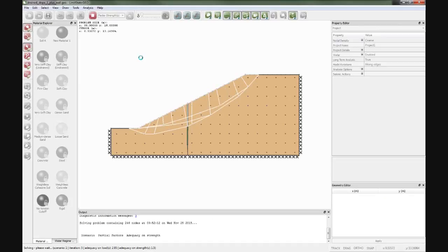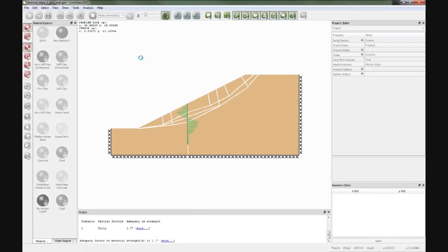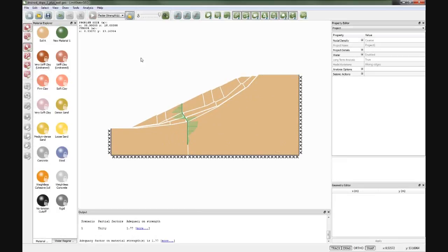The software will simply cause a failure mechanism where that sheet pile wall bends. So you can determine what sort of bending strength is required to avoid a ULS. And do remember this is ULS software, so that's required for ULS. You do need to check SLS as well.